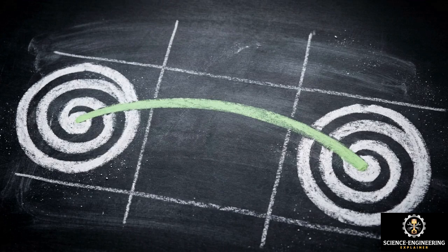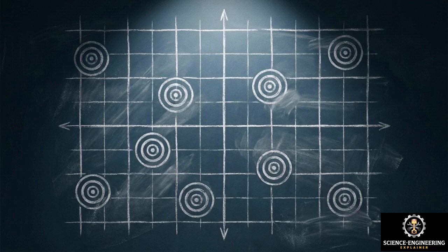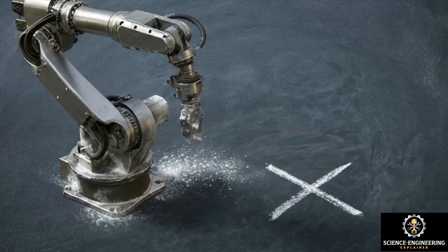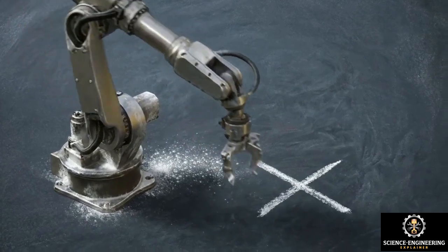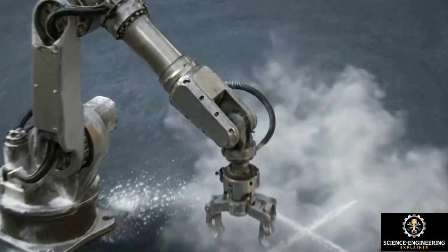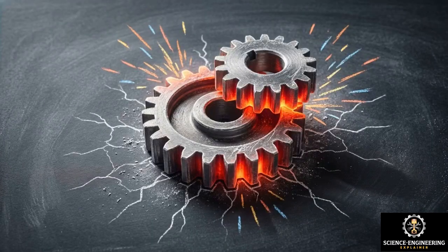SLERP operates perfectly between two isolated points, but if a task requires motion through a continuous sequence of waypoints, chaining standard SLERP segments together creates sharp C0 continuous corners at every single node. These sharp angular discontinuities translate into infinite acceleration spikes. As the machine tries to instantly snap to a new velocity vector, it generates severe mechanical torque, damaging the joint motors and degrading the hardware over time.